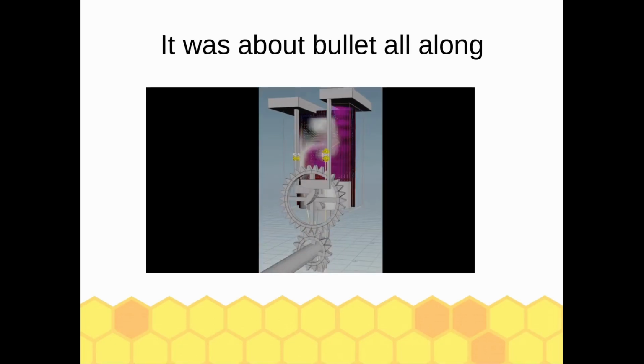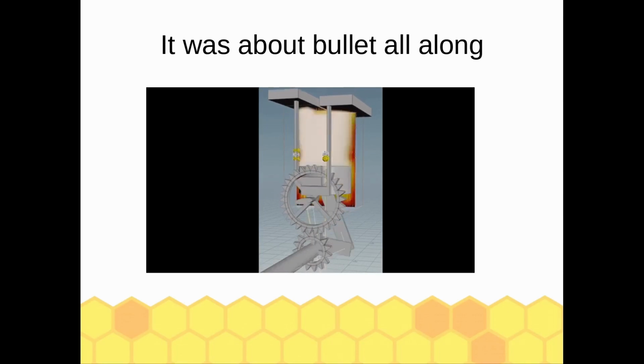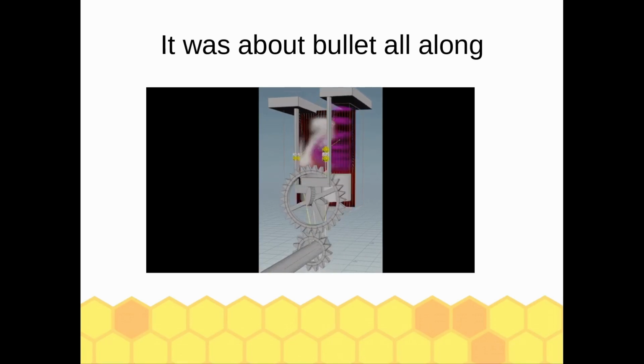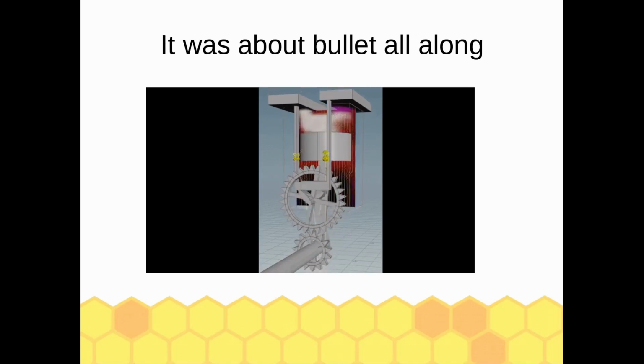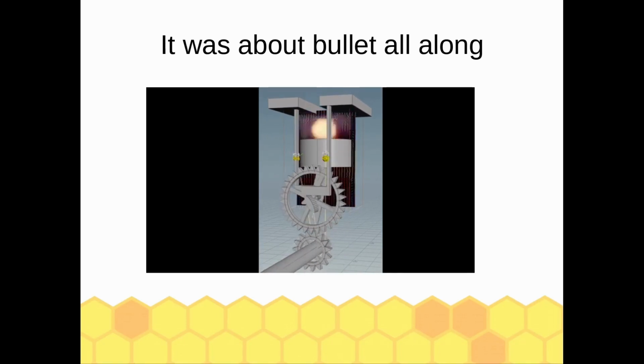The next one is that thing about the car in a cube. If you think about it, that video was all about Bullet. Sure, there was some pyro simulation, but whenever this GIF plays, you will see that it's actually a stock pyro sim with just feedback enabled. There is no magic here. The valve to the right hides the fuel source field that gets sucked in by the piston that operates as a collider, and the smoke gets pushed out from the left valve and gets sourced into another purely decorative smoke simulation. But here, pyro just pushes on the Bullet object, which is the piston. And yes, the feedback in Houdini is another topic that is interesting and way underused, but that would be a topic for another discussion.